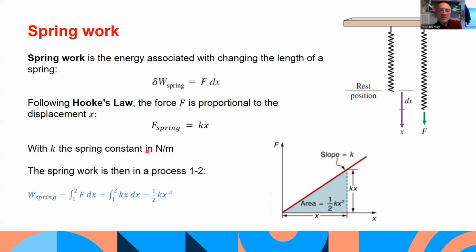The spring constant is specific to different types of springs, taking into consideration the geometry, the size, for example, the length, the coil diameter, the thickness of each coil, the material type as well, and the nature of the spring, whether it's a compressive spring or a tensile spring or even a torsional spring. All of that's taken into consideration to define the spring constant, which we would need to factor in when we're trying to understand the force by displacement for a particular spring.